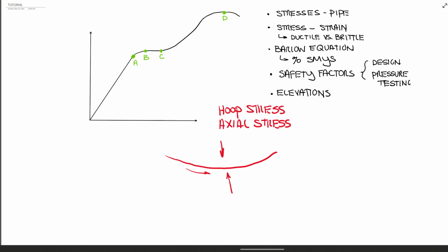If you've ever bent anything, you can tell that on the outside of it, it's in tension, and on the inside here that I just marked is in compression. So although axial stress is certainly a problem, it can be aggravated by mishandling the pipe out in the field, in combination with when it's in operation, if you backfill it or maybe banana that thing, so it makes it even worse. Okay, so the second thing I want to talk about here is ductile versus brittle,